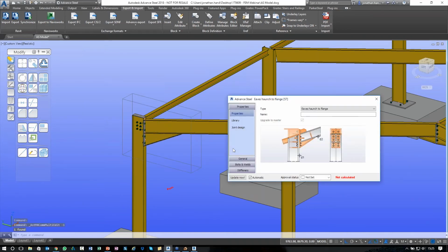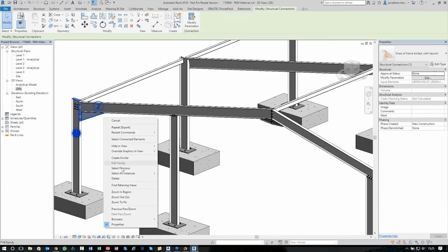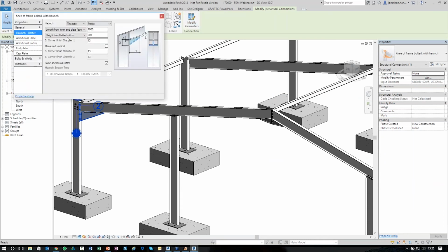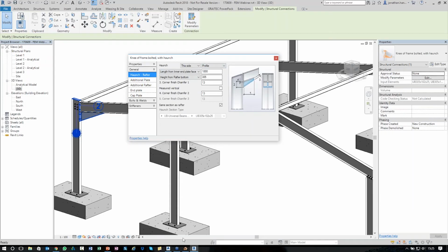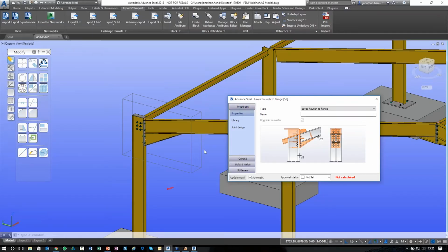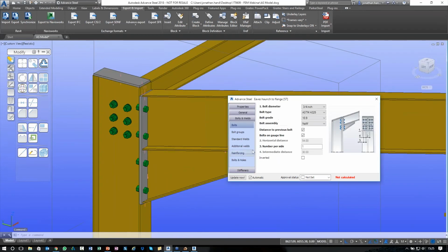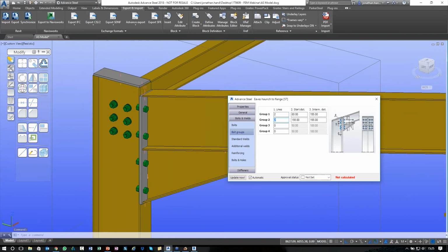And because these are standard connections, we just go straight to our advanced steel tools where we can start to modify, and I can start to just duplicate what's happening throughout my model. So even if the guy in Revit gives you a file with one connection, it's still way quicker to do that. And what you can do is, if you're familiar with advanced, we can go in and configure all the connections. So I'm just going to copy some connections about the system. You can see that sometimes, depending on what we have copied, it won't always work.